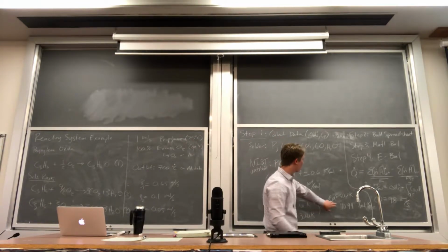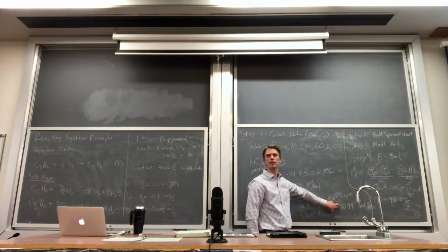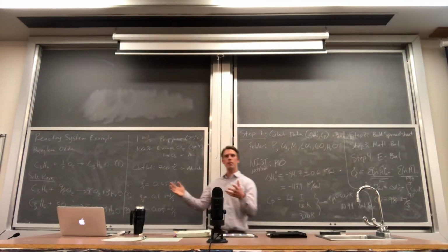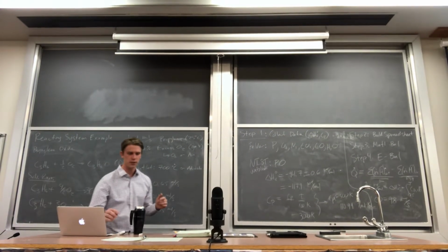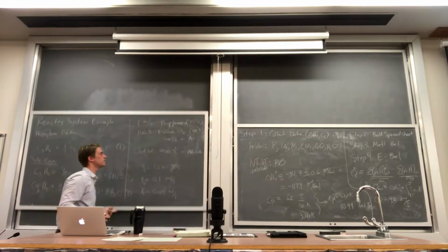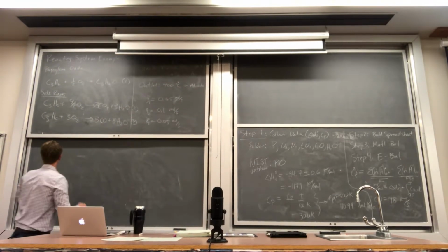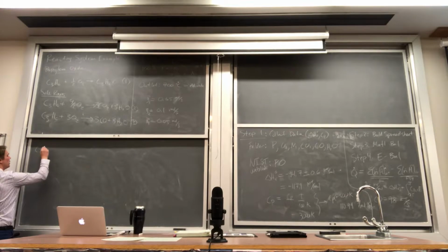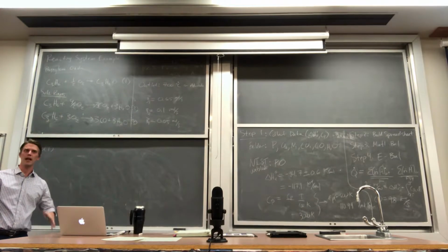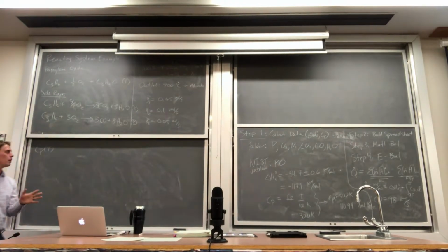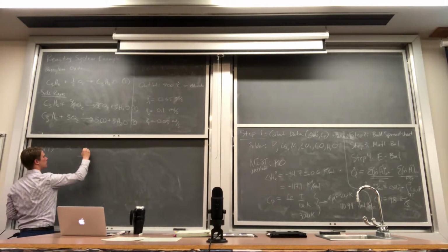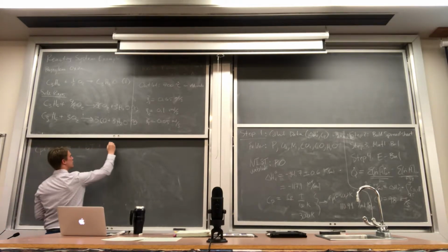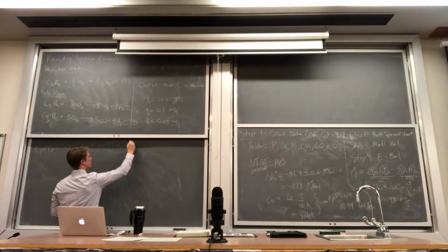Oh, one other thing that I wanted to mention here, on the propylene oxide, here, I grabbed one value of the heat capacity. And so in order to simulate that it was a constant heat capacity, I just put these higher order terms set equal to 0, right? Because the correlation in the book is that C sub P as a function of T, right? Now we most often integrate the heat capacity, but in reality, this is just the heat capacity correlation, right? This is the heat capacity as a function of temperature is equal to some A coefficient plus B times T plus C T squared plus D T cubed.